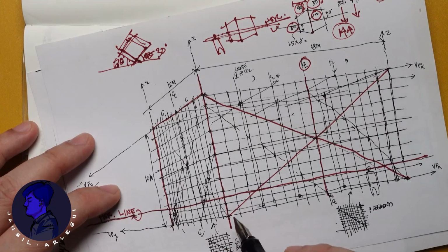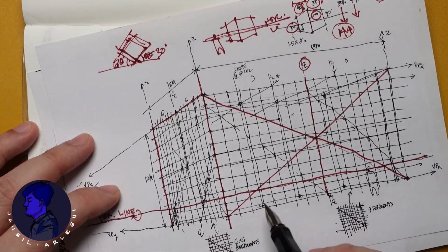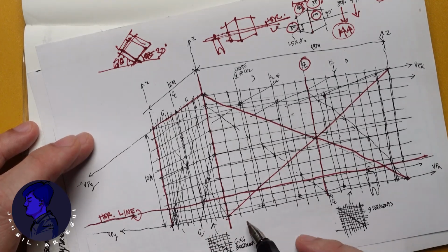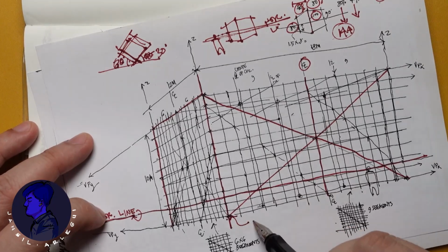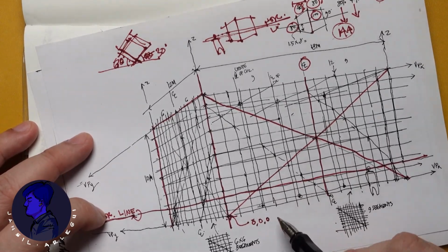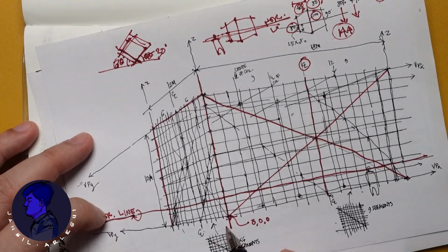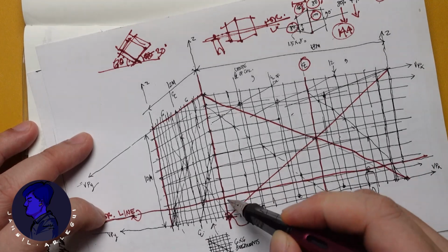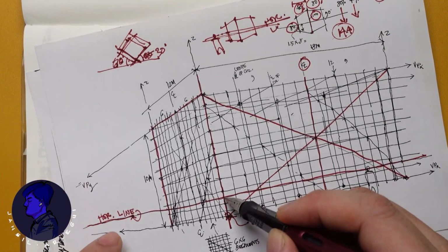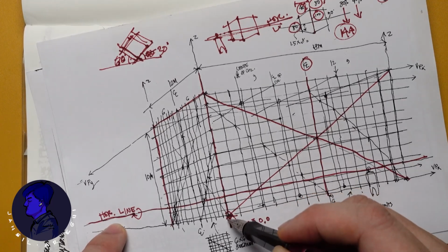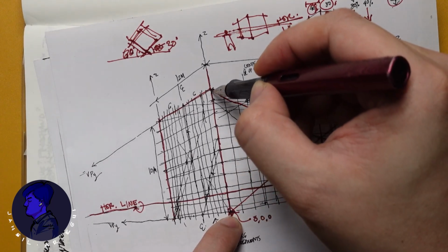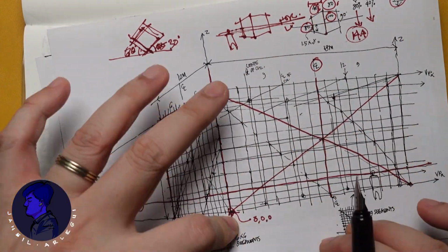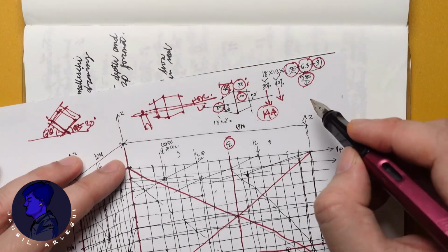One thing to take note of is where you start from, exactly the horizon line, and how you relate the ground, which is the 0, 0 coordinates. That would be the starting corner of this framework. You measure 1.5 meters from the horizon line down to the bottom, and that's when you start measuring 10 meters for this framework, or whatever total height you need.